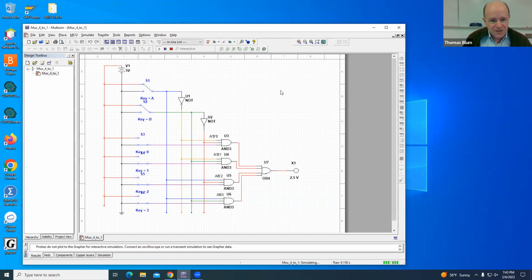And so that's it. That's the job of a multiplexer. There are inputs that correspond to the address or the select, which are going to pick, and then the other inputs are the data. So you have some sources of data. You're going to use the select or the addresses to pick one of them, and then that is the one that gets through to be the output of the multiplexer.